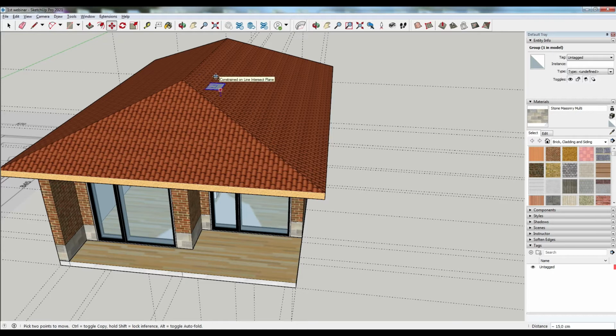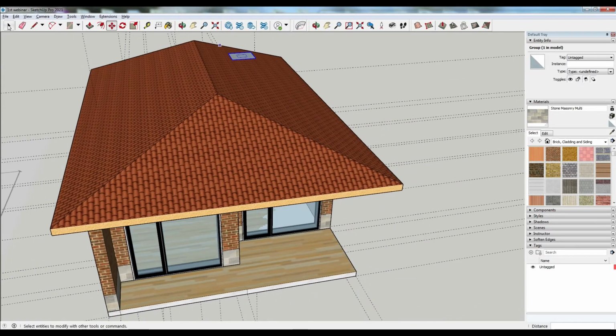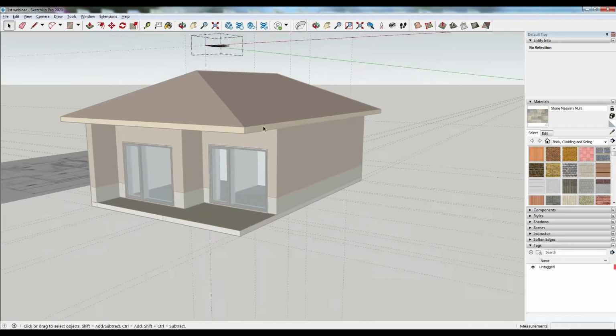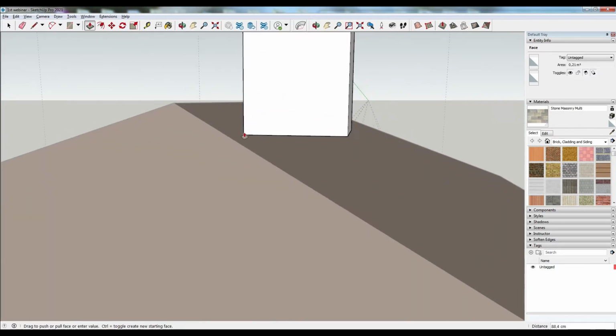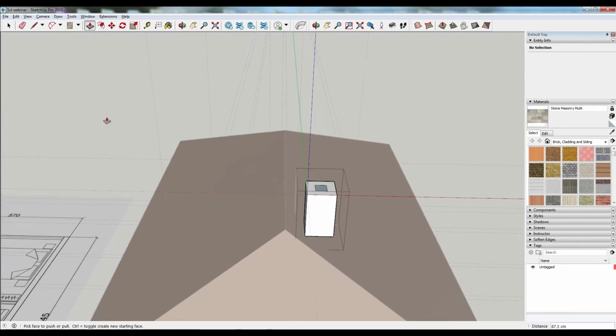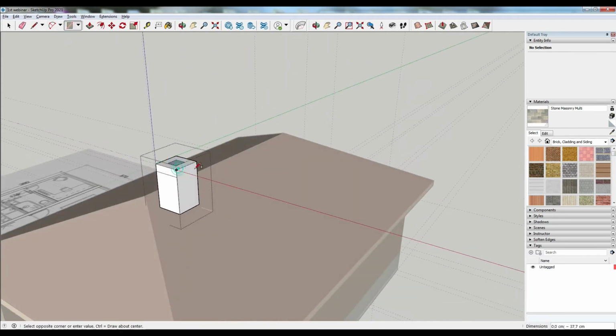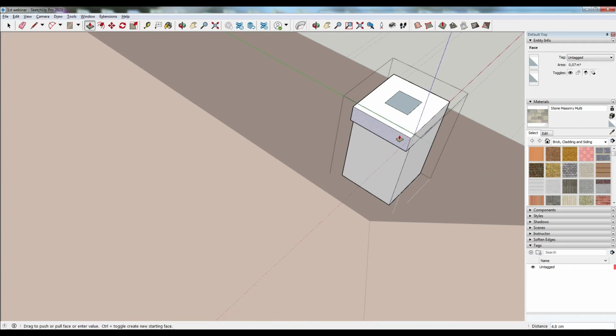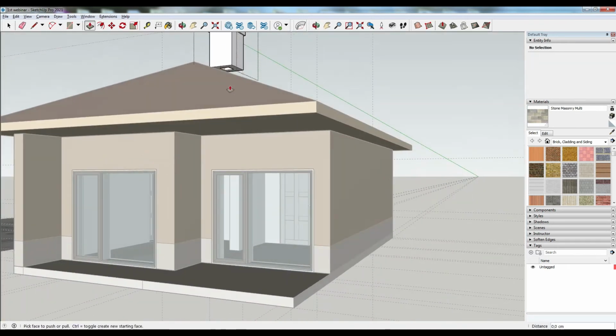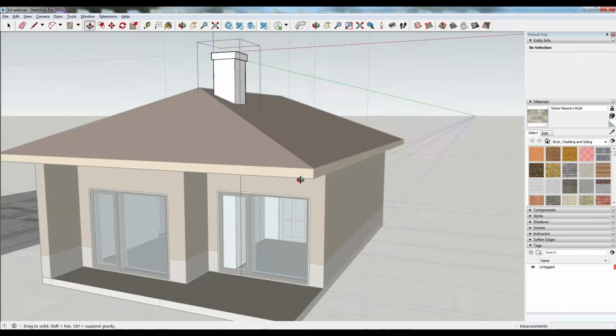Now I will enter the group and will make it in 3D. You see all the other elements that are not in the group are in grayish colors. Using the push-pull tool, I will make it a 3-dimensional object. Then, for an even more realistic look, I could make some extrudes on the upper part with the rectangle tool, and then with the push-pull tool given a size. Then double click on the other surfaces and they will automatically become extruded with the same size.